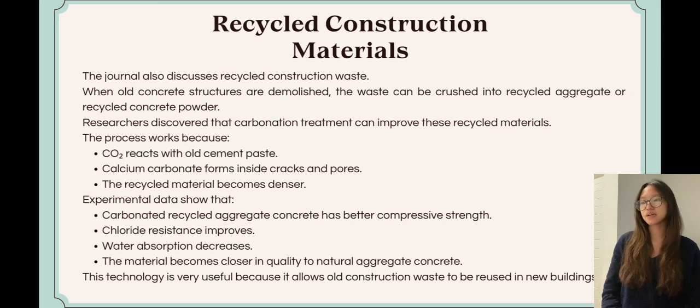Experimental data show that carbonated recycled aggregate concrete has better compressive strength. Chloride resistance improves, water absorption decreases, and the material becomes closer in quality to natural aggregate concrete. This technology is very useful because it allows old construction waste to be reused in new buildings.